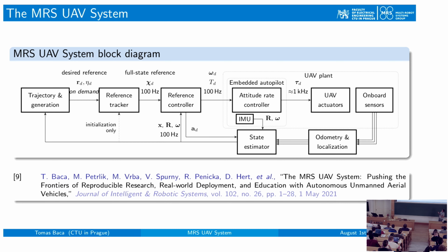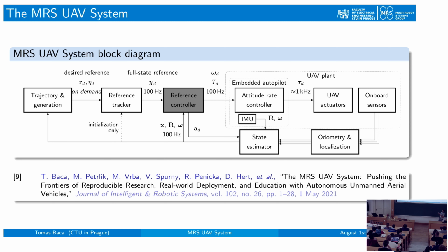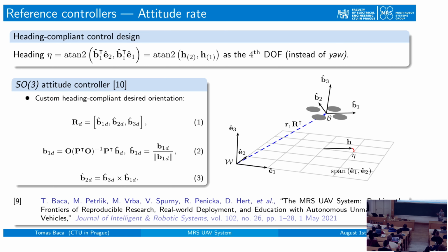So back to the system description of our system. The first important block which we have in there is feedback control. A lot of people think drones are only about feedback control, that you need to solve the control problem and you've solved everything. It's not true, but it's a very important part of the system. It keeps the drone moving according to a reference, which is supplied at 100 Hertz. So someone has to give the drone 100 times a second a reference in acceleration, position, velocity, and the feedback controllers make sure they follow it.